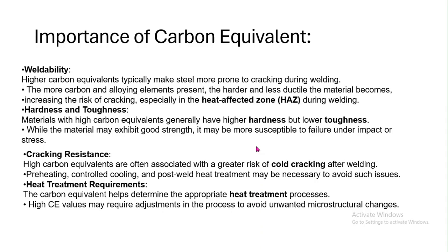Then the next thing is cracking resistance. If the carbon equivalent value is higher in the material, there's a greater risk of cold cracking after the welding. So to avoid these issues, preheating, controlled cooling, and post-weld heat treatment are necessary.